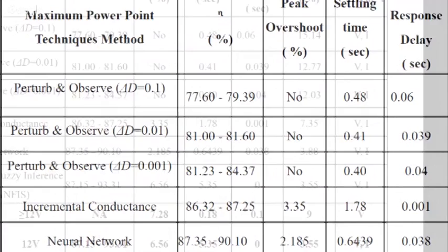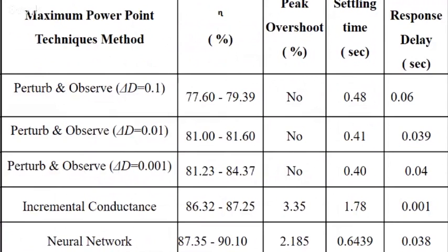You can see here, first perturb and observe with duty cycle change in the ratio of 0.1, the step of 0.1. I told you we are perturbing the system. Do you remember that? Perturb is in what range you will change the duty cycle. Only slightly you will change, or you will change more. So you can see here, when we change more, the efficiency was less. When we change very less, your efficiency has improved. That is also clear from this.